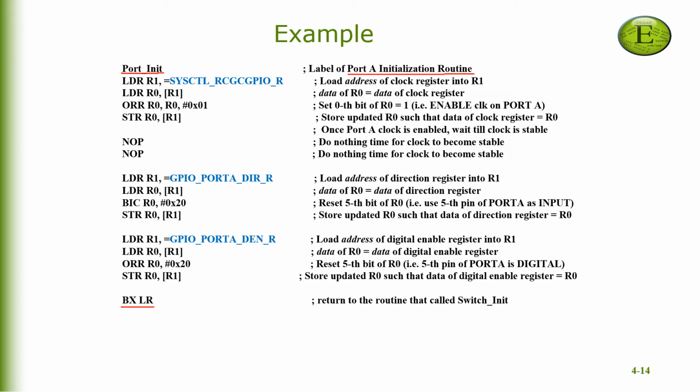Then, once the address has been loaded into register R1, the next instruction utilizes that address and invokes index addressing mode to access the data of the clock register.